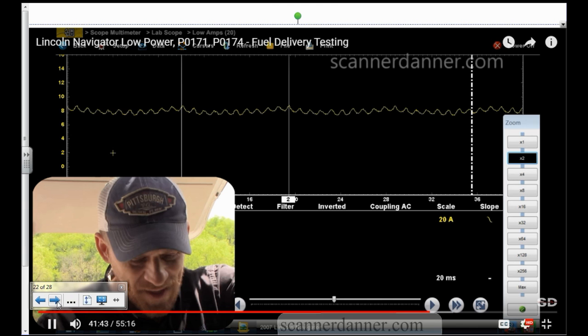Okay? Especially on the side-mounted ones, when you have a side-mounted brush, so the brushes come in this way, and they would sit on the side of that pump. I can't draw this like rounded, but this is actually a round piece, and these are square cuts, so they never really make good contact until they seat in. Just be aware of that. If you're ever doing pump current measurements on a scope, the new pattern can look messy.